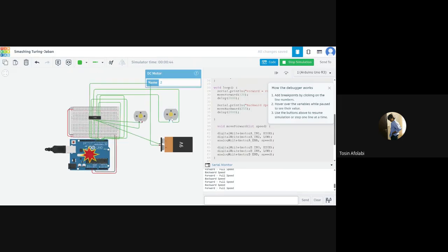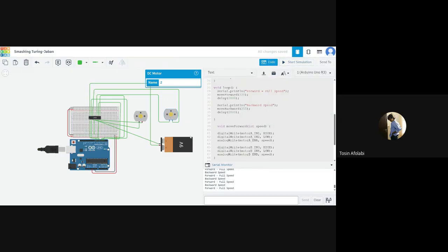Looks like I don't know if it's working, but it's saying 0 RPM. That means it's not working. So our code is saying something stupid here. There's going to be a problem with our connection somewhere. This is the worst part of doing something like this, debugging. So we stop our simulation, stop damaging our Arduino. Then I'm going to look at the problem. This total current running through is 225. Maximum is 200. So I think there's a mistake in one of these connections.